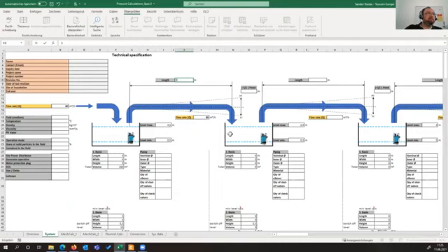We select, as an example, 50 meters. So here we can also add a positive head if the piping is rising, or a negative head if the piping is dropping down. I think we will calculate with a positive head of about 30 meters for our calculations.